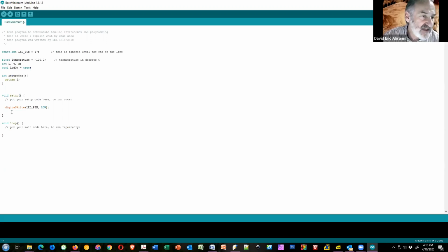All right, so down here, I say, gee, I've got an integer I, so I say I equals. So this is a function call. How do I call a function? I just use the function name. So what happens here, I come down here, I execute digital write LED pin low, so pin 17 gets set to 0.